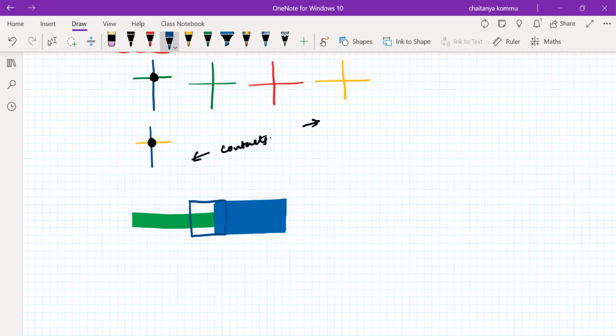This is the overlap region for the blue color, as well as the green color also I have to consider. So 4 lambda by 4 lambda, green color on top of it. Okay, so therefore I have to draw something like this. This is how we need to write. Blue color also I have to write in this way only. Vertical lines I have to consider. I have to take 2 lambda by 2 lambda contact cut.